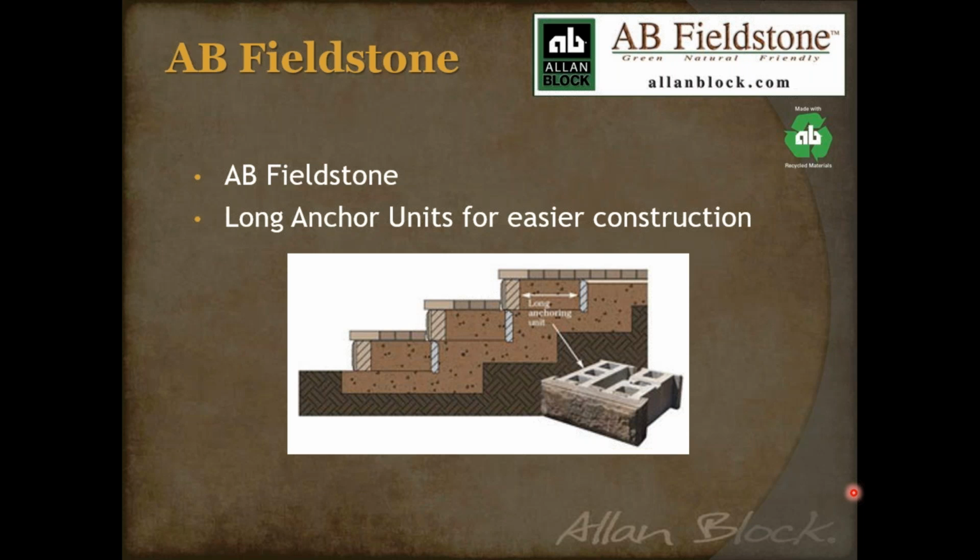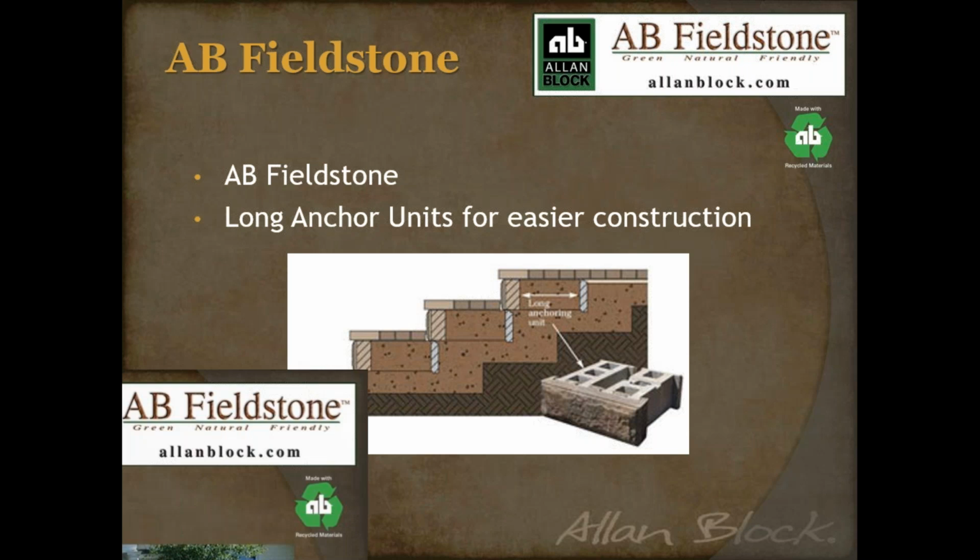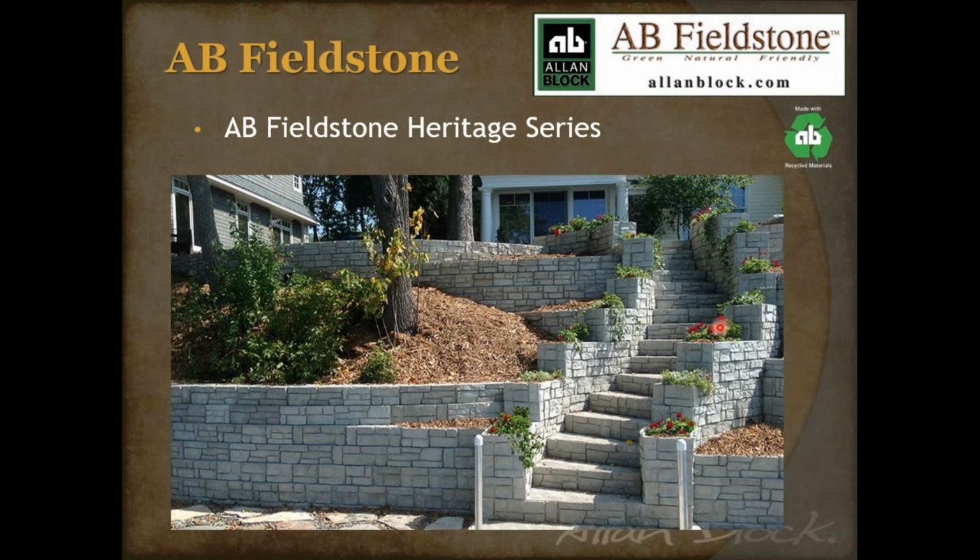That's one of the reasons why I'm not trying to push fieldstone, but one of the advantages of the long anchor unit we have is now it's 24 inches deep. So therefore you can rest the next block on top of the one below it, and it just helps you with that layout, helps with that base installation. And that's what they did here. A beautiful project where they just used the long anchor units in the stairs so the next rise could be put right on top of that. The way they finished it up, since it was kind of a switchback and non-uniform, they just poured concrete in the cores and kind of finished it off right on top there as a great way to finish that set of steps. So keep that in mind.